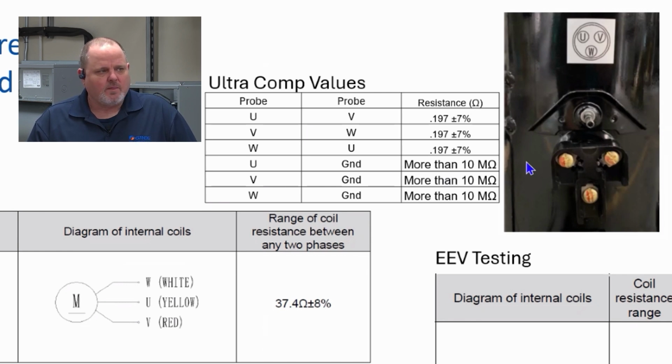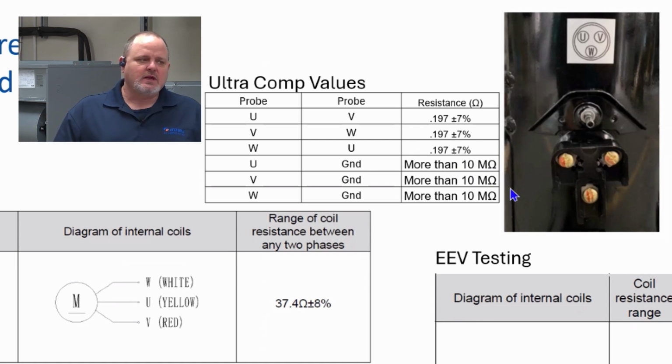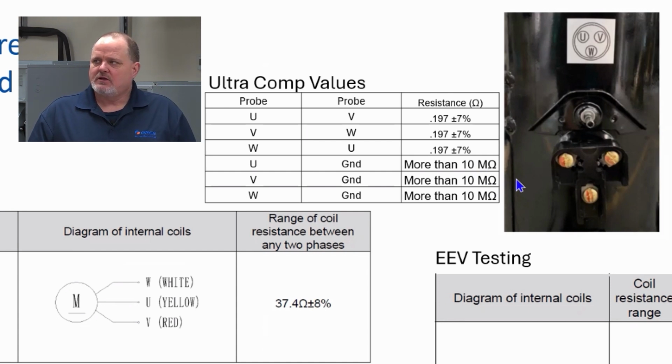Measuring the ground. Be very careful when you're measuring resistance from a compressor terminal to ground. I always use just a copper pipe coming out of the compressor. That's an excellent ground source. Make sure that meter's not reading in mega. A lot of meters, even when you have it on ohms, will give you a reading, but then it'll also have that M there. It's telling you it's reading mega. If you're reading mega ohms, that compressor's not grounded. If you've got a grounded compressor, you're going to read resistance to ground in K ohms, like 1,000 ohms. That means you've got a grounded compressor.